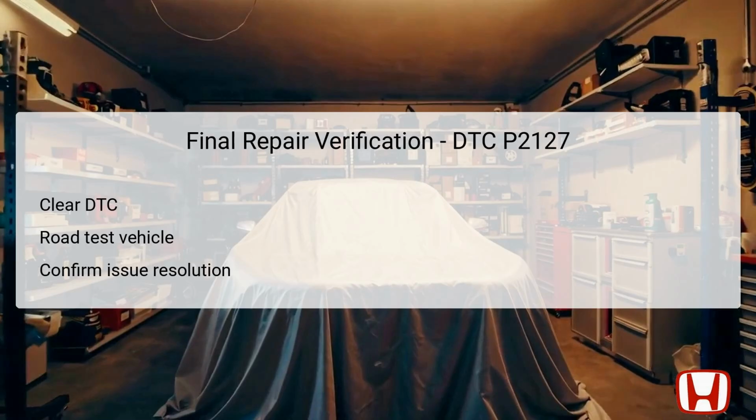Begin by using the HDS to clear any stored DTCs from the vehicle's memory. After clearing the codes, it's critical to conduct a thorough road test of the vehicle, paying close attention to the accelerator response and ensuring that it behaves normally. During the test, observe for any recurrence of the P2127 code or related symptoms.